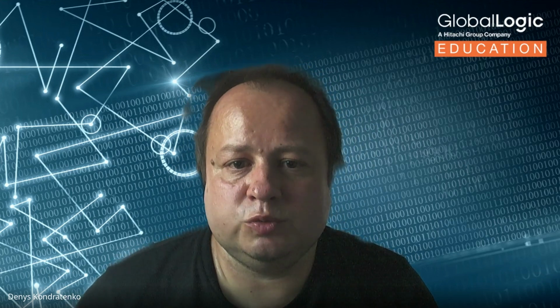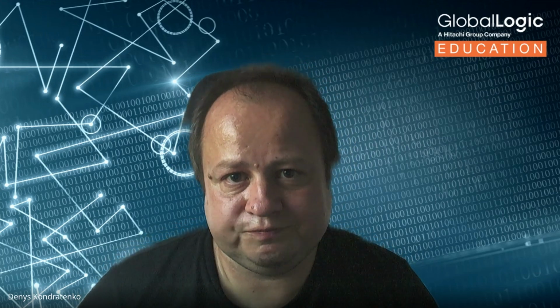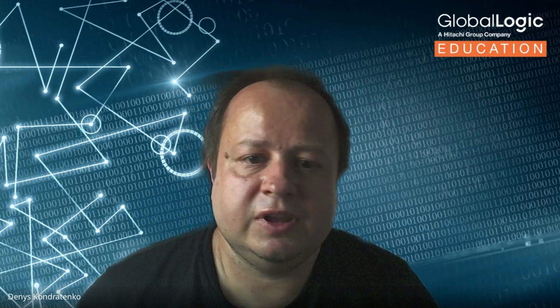So soldering is a must. You need to have experience working with a multimeter and be able to measure current, voltage, resistance, and understand the difference between them. You need to have experience working with an oscilloscope, and especially if you work with devices that communicate with each other, you need to have experience working with logic analyzers. It's a really cool device, especially if you need to create your own communication protocol or debug some kind of proprietary commercial protocol that you are not aware of how it's working.